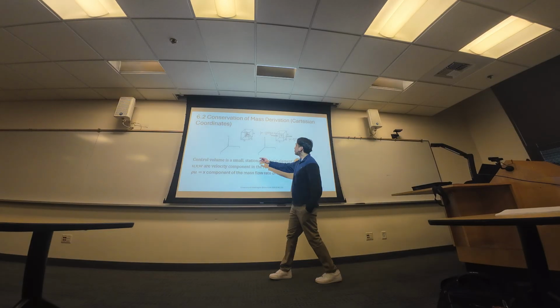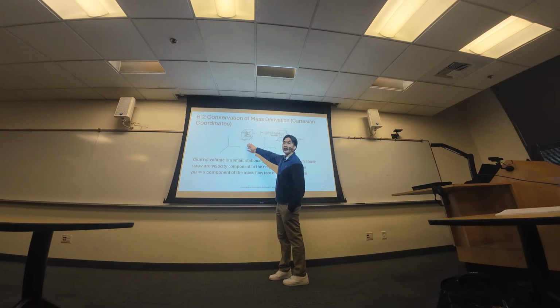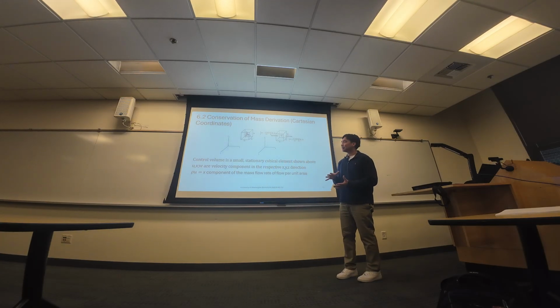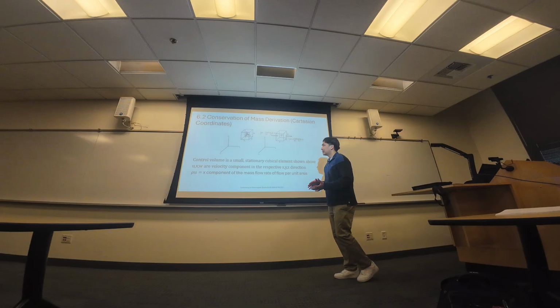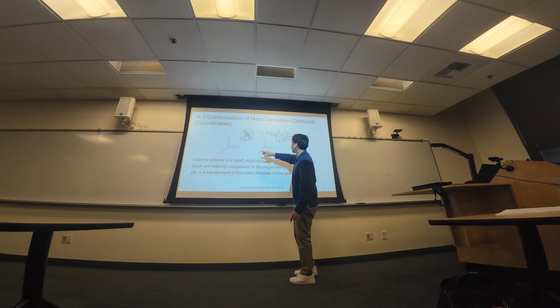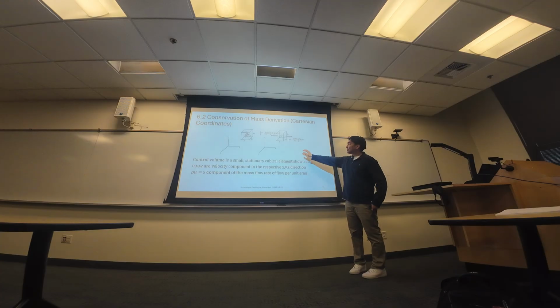Okay, so we start off with this cube here, right? Delta x, delta y, delta z. We have these because it's a fluid and it's changing, so the dimensions are changing. This rho is usually written in the middle because that's the center density of the particle. This is your velocities in the respective direction. And these are the equations of essentially your mass coming in and out.